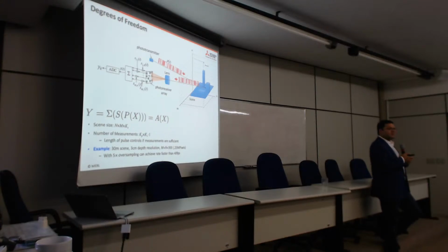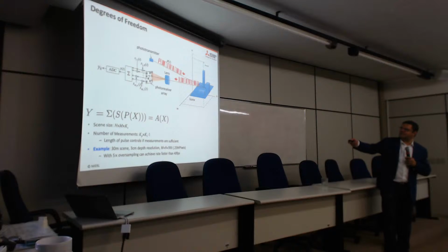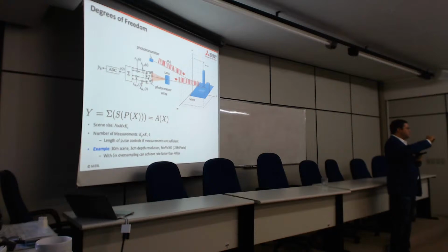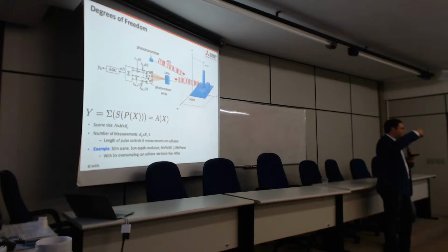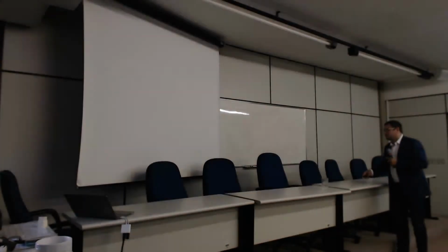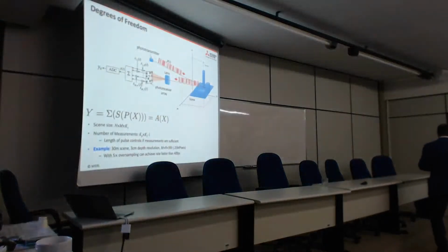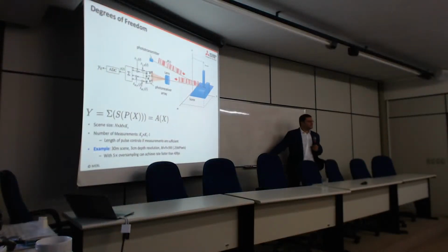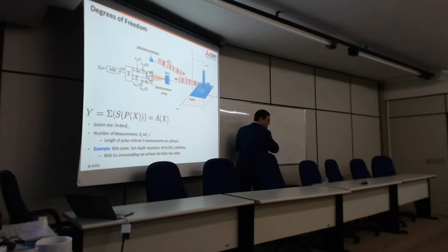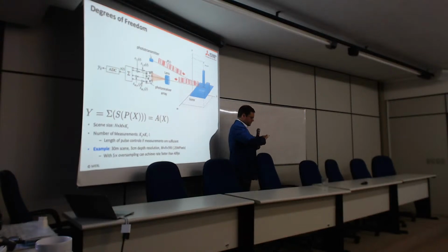Here's the thing: what you get here is not just your code, it's your code multiplied with this. So you need the product of those two codes to be orthogonal to shifts of that code product with the same product. I'm sorry, I didn't get that. Let's use the board. It's kind of like a CDMA system. It's CDMA, exactly, but you also have the depth component.